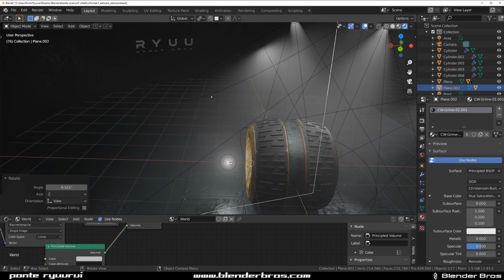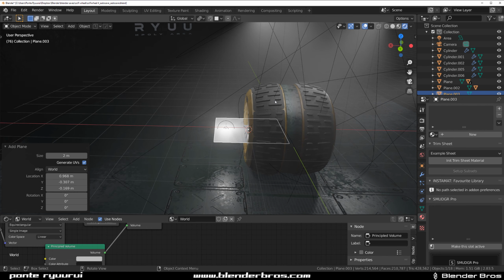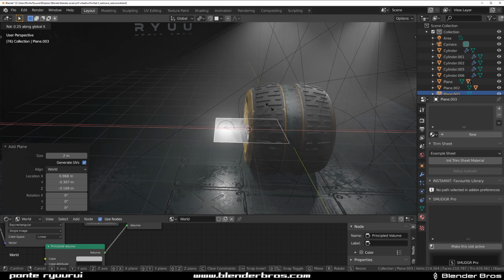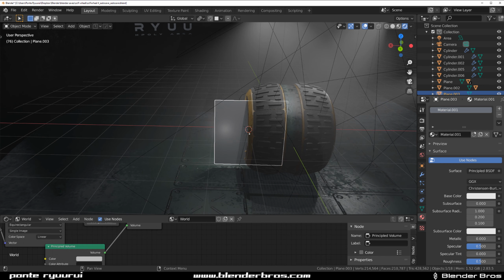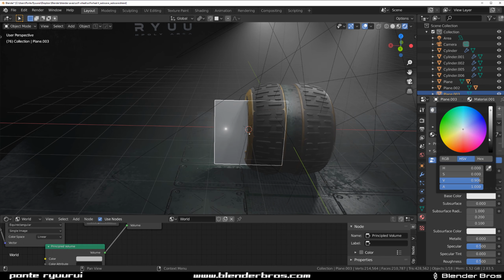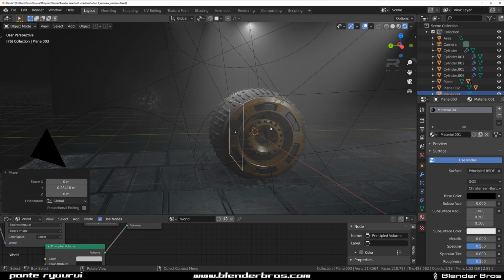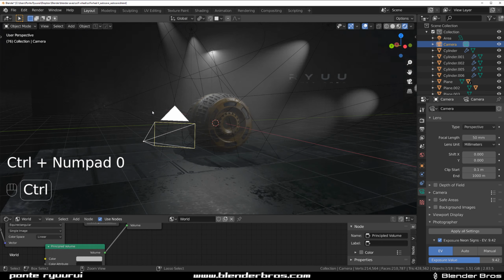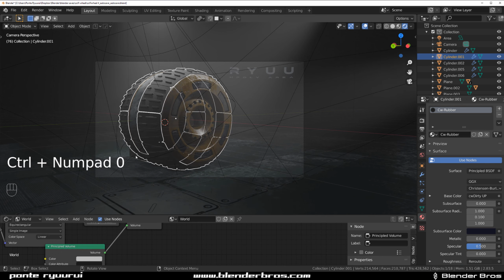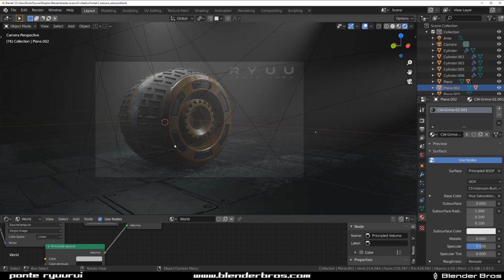Also, this light here needs a flag, because it's spilling on the left side. So we're gonna grab the plane, RX90, GY, move it in here, and drop a color black, so it's non-reflective, yeah. And GY, move it somewhere here, like this. So it's gonna flag this area. Flag this light from spilling, but it's a little bit too close, so we need to move it inside so we don't see it. There you go. Now it flags it, you see.